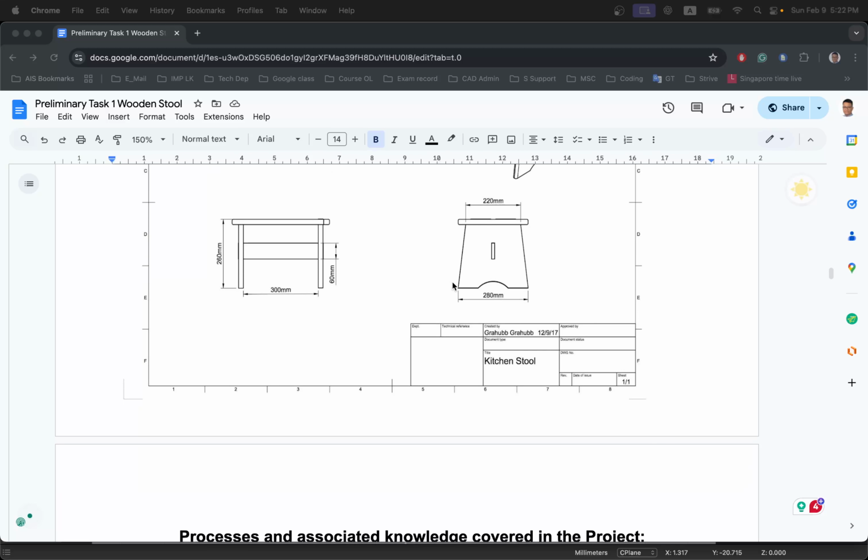When it's done, next step. To always easily look at the center line of the whole project, I recommend that you turn on the gumball, select the piece that you just created, and click on the center Y dot here and snap to the 0 point.